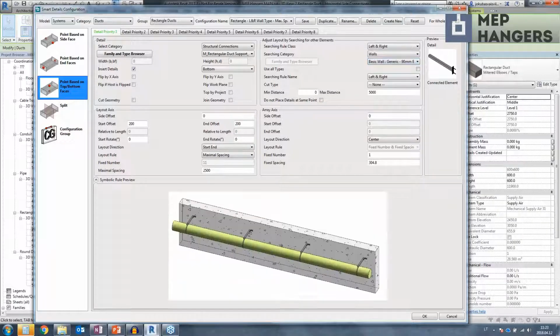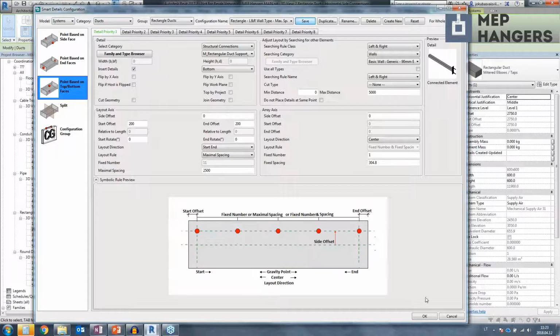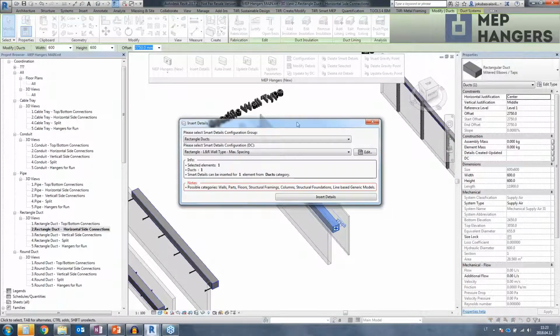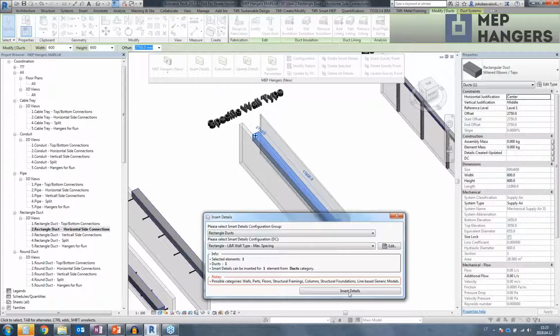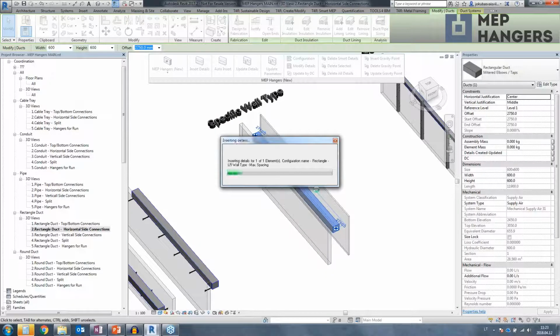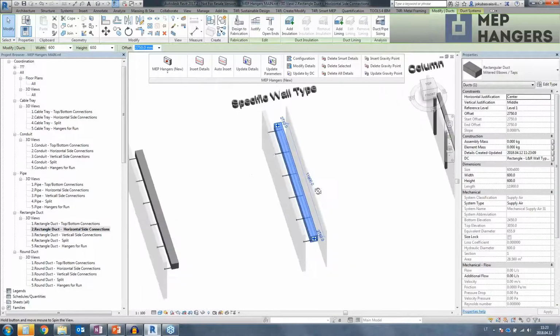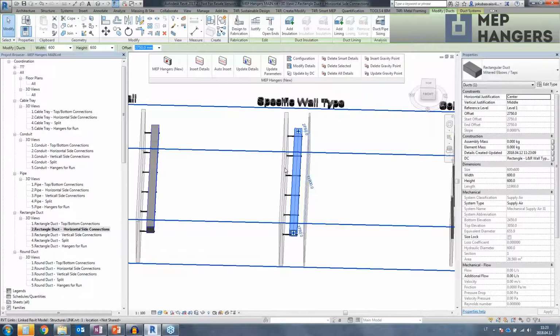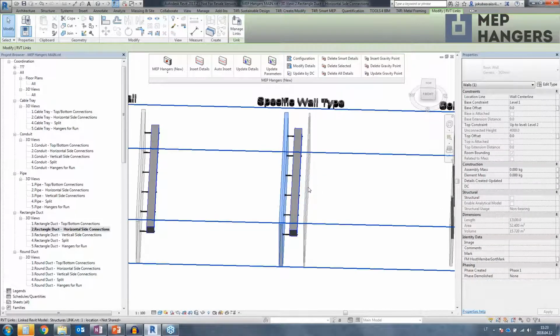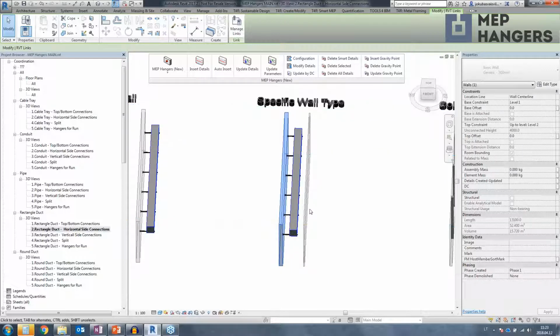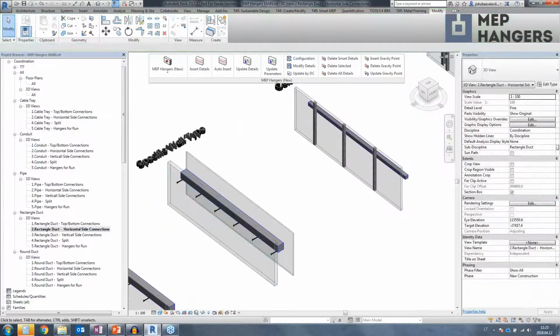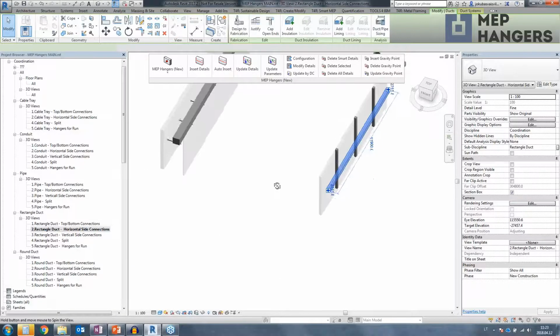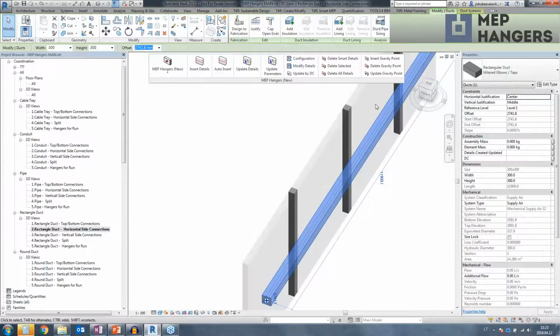For example, this one, and I'm saving that, clicking OK. So I'm going to connect to this smaller wall right now. Okay, maybe this wall was chosen. So it decides by the type, it decides to which side it should rotate the family and stretch the family.